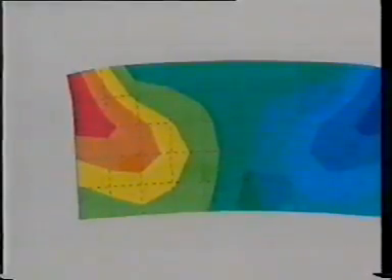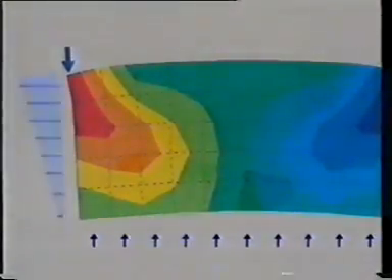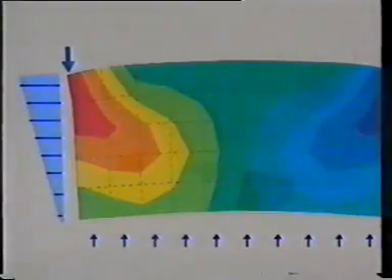Each color in this computer picture represents a certain interval of shear stress due to horizontal wind loading. It shows that the stress distribution at the end cross girder can approximately be represented by a straight line.